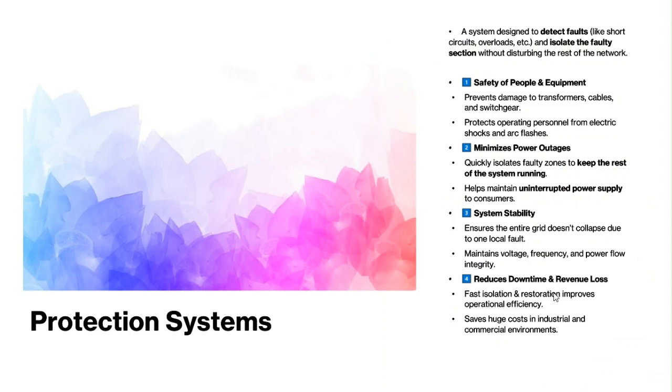Now, in case of a fault, maybe the protection system will get damaged, but it will save the equipment, which costs 2.5 crore approx. It means it is saving us from the potential loss. It also saves the downtime. If the transformer gets damaged, then the downtime would be very high as compared to the protection system. So it also increases the reliability of the system, and at the same time, it also saves the persons who are operating there from getting shock and things like arc flashes.